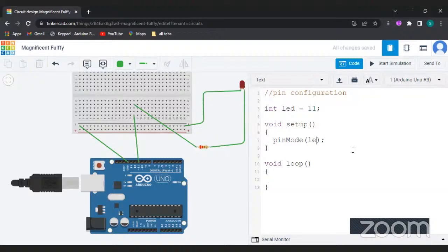Good. So the next thing to do is to write, let, and give argument. Well, this is another part I have to take note of. Now, a function can actually expect a parameter, or we call it argument. Now, for the setup function you see here, and the loop function, they expect nothing. You see, inside these brackets here, there is nothing within the bracket. The bracket is empty. But for the pin mode function, I'm putting two arguments, the LED and output.